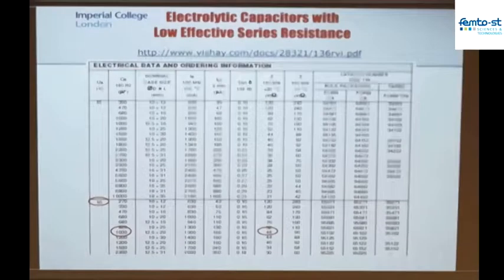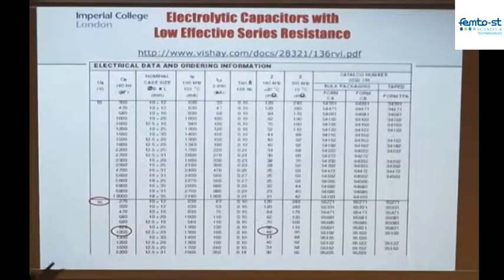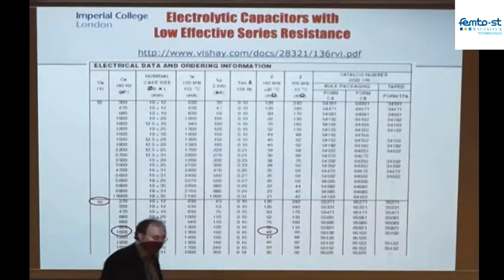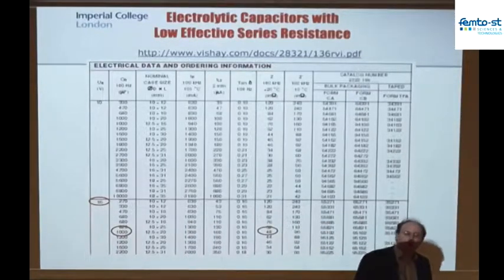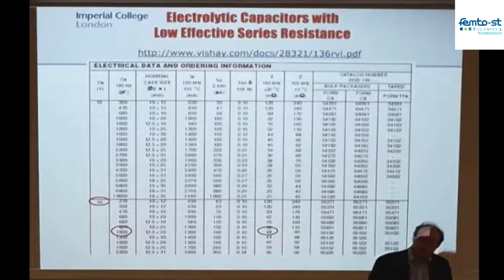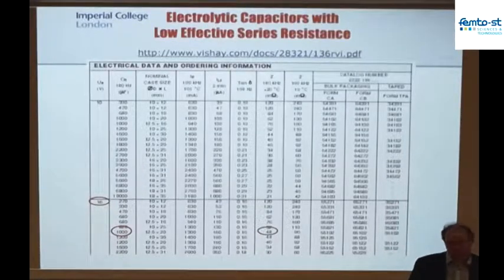Okay, so effectively it is a question of understanding the components, understanding how the components are not perfect, calculating the voltages that you get because of those non-perfect components, and a trade-off between pushing the frequency high enough to make sure that the converter is small enough and the voltage quality is good enough, but not so high that the losses become too high and the system gets too hot in a large system, or too inefficient in the case of an energy harvesting system.